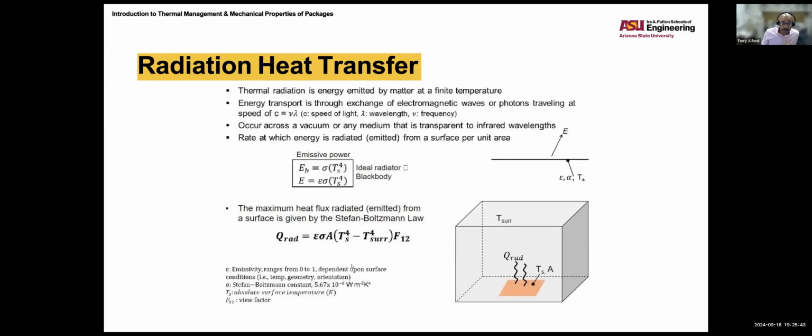Now I go with a different approach. Now I'm going to go with my die, as opposed to doing convection on the top. I am going to go with a TIM here. And I'm going with a large heat spreader. So in this I can design to move most of the heat in a given direction, preferably up through the TIM into the heat spreader, where I will get convection to cool it as well.